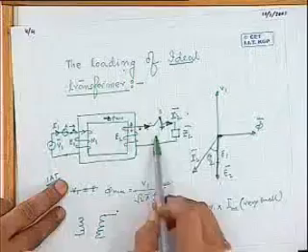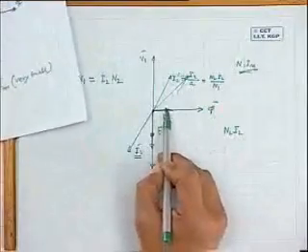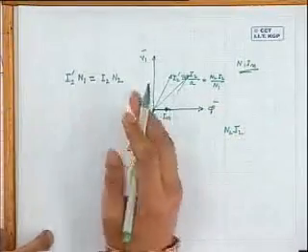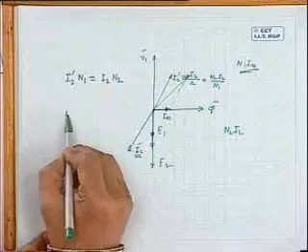Because of what? Because it has to satisfy the KVL equation on the primary side. The flux level gets decided by the supply voltage and frequency. Flux level is fixed, no matter what you are doing on the secondary side of the transformer. So this IM I brought in, but let me go to that ideal transformer.